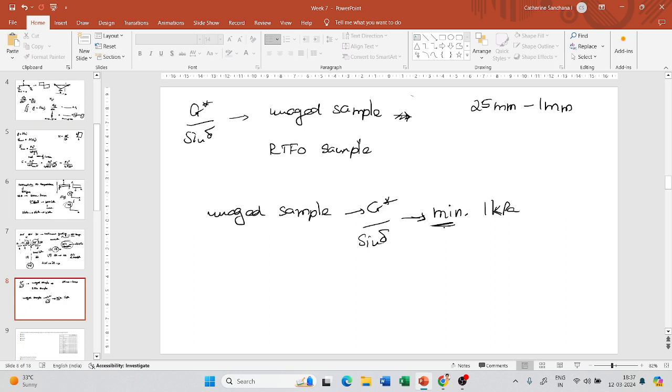Because at high temperatures the bitumen is very soft and so it is more prone to rutting. In order to resist this rutting, the bitumen has to be stiffer, right? So it should have a minimum stiffness, stiff enough to resist rutting.